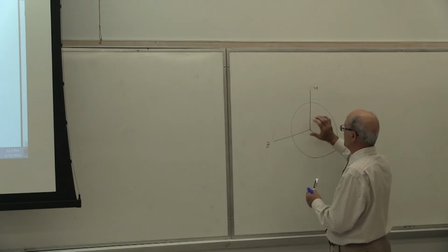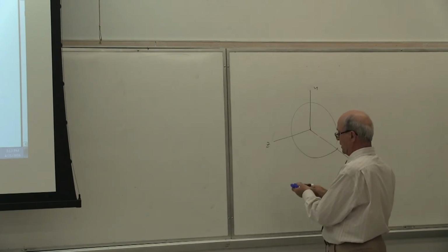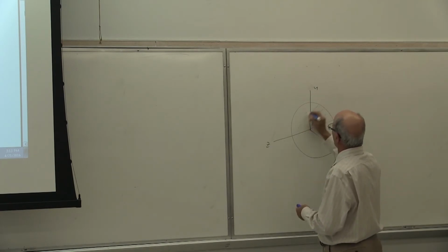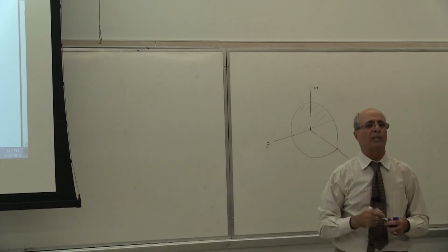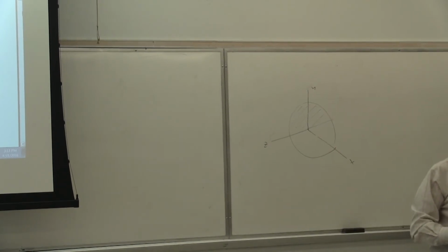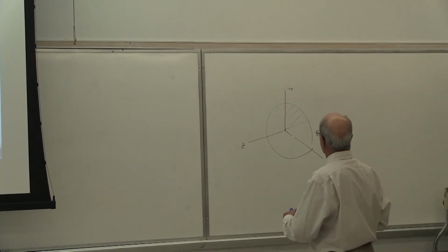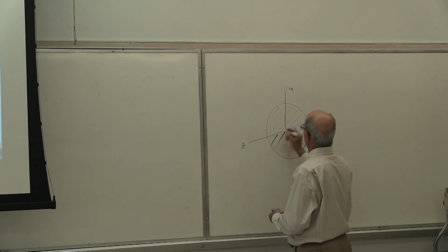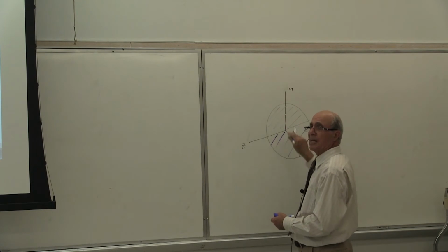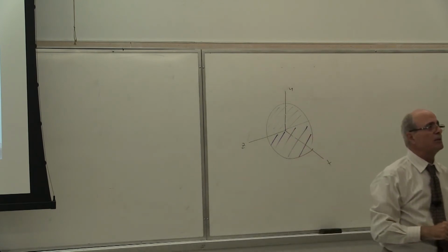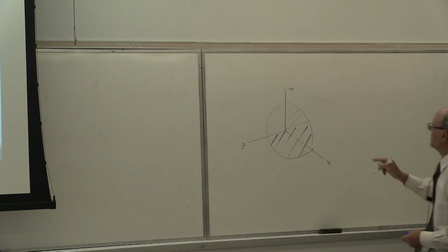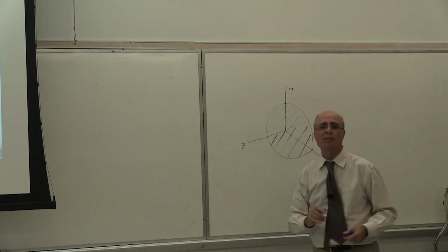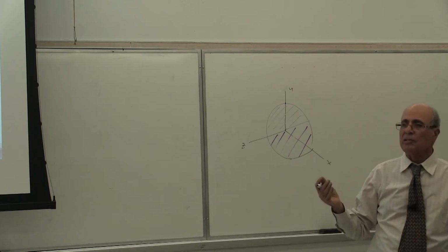If this is Mz here, that means I'm going to have compression at the top. All the blue part is the compression side. Yes or no? Yes. And all the purple side is the tension side. Everybody knows that here is 0. As I go up, it increases, and as I go down, it increases. Yes, so remember ME218, correct? However, this is the maximum for Mz. This is maximum compression, and this is maximum tension. All of us know that, correct?